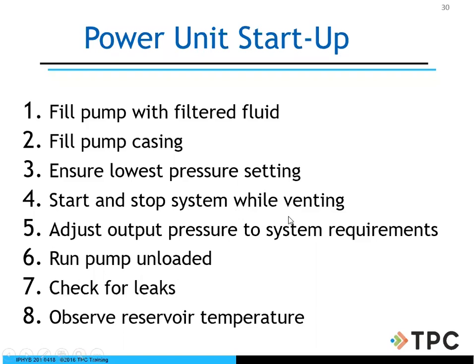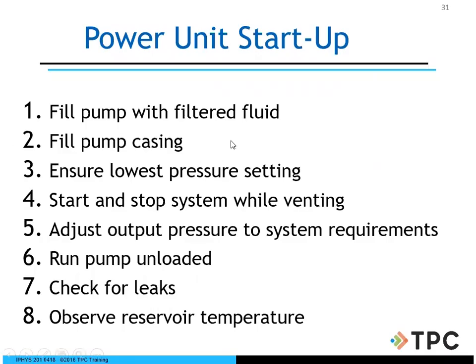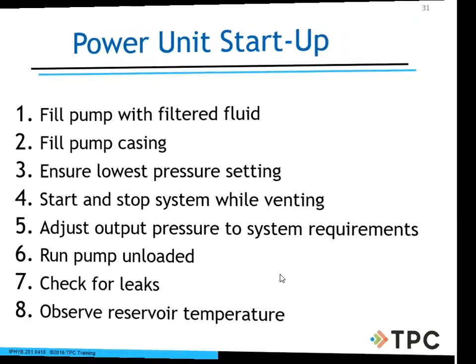Start and stop the system while venting, adjust the output pressure to system requirements, and then all the way through here, check for leaks and make sure you don't have any leaks in your system. If you have something leaking out of your hydraulic system, you have contamination going in that same hole, 100%. So you don't want that to happen. Again, fill the pump with filtered fluid. Run the pump unloaded, so without a load, and observe reservoir temperature at all times.